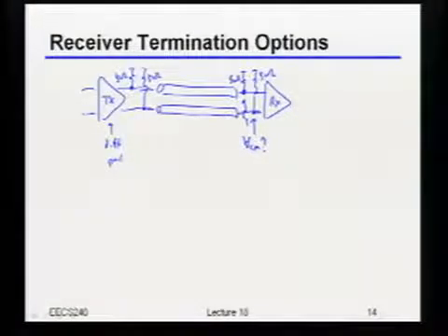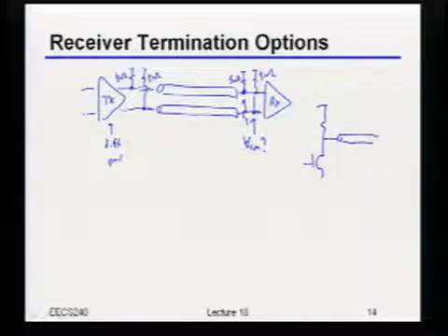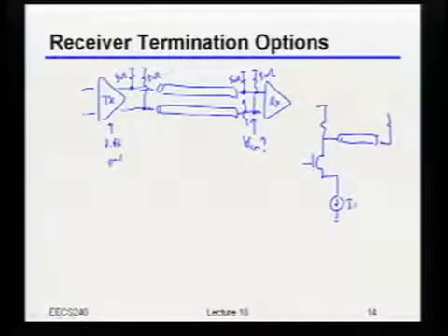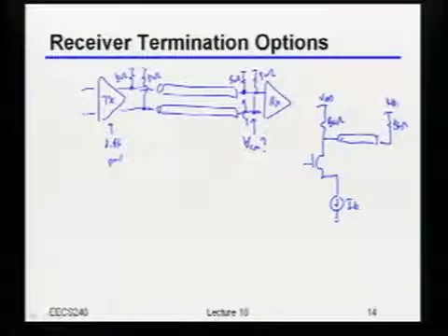It's going to be set by the transmitter. What is that output common mode of the transmitter? Maybe I'll just draw the half circuit for the transmitter with the receiver. So I've got some IB, I've got some 50 ohms right here, got another 50 ohms right there, and this is some VDD. So what is that common mode going to be set by?